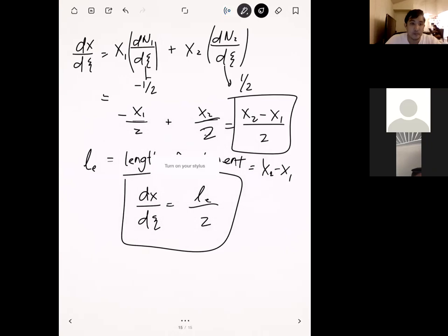Another question, by the way. I'm still working on the homework, and I had a question about it. Remember the video and the ANSYS activity about the bike crank? You said that we need a fixed support in one of those holes. But I thought it should be a pin support, because the crank is just rotating. It's not moving in the X and Y directions, but it's rotating. So it should be a pin support. That's what I think.